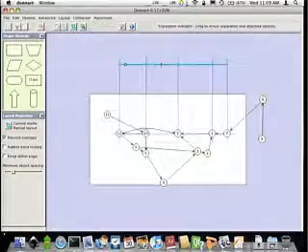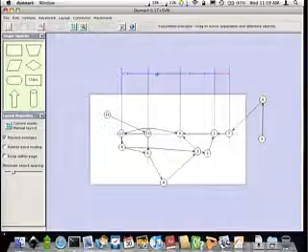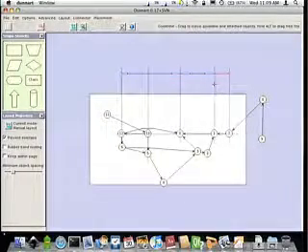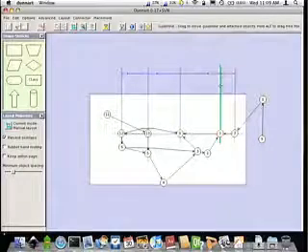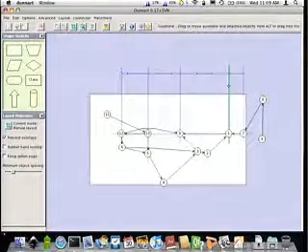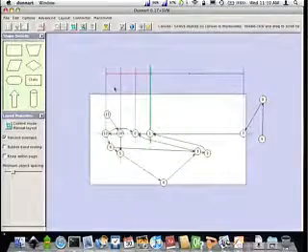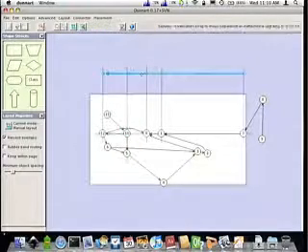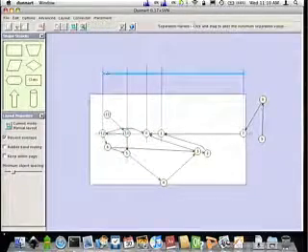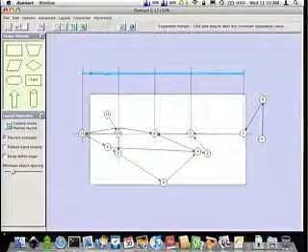And again, we get an on-screen indicator that represents this separation. You'll notice it glows red when one of these constraints reaches its minimum size and starts interacting. You can see as they bump into each other, this kind of occurs. Also, you can click on the relationship, obviously remove it, but also resize this minimum separation if you desire.